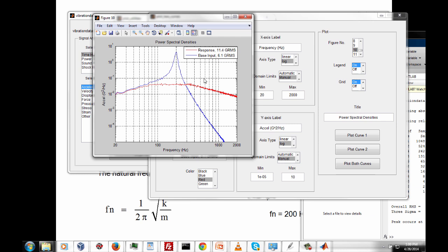Now, for the spring mass system, sometimes we refer to that as a mechanical filter. And as you recall, we use the Smallwood algorithm, which is a ramp invariant digital recursive filtering relationship. So the filtering refers to two things. It refers to the fact we're filtering out this high frequency energy.